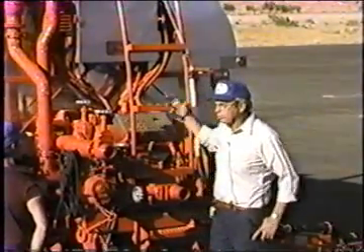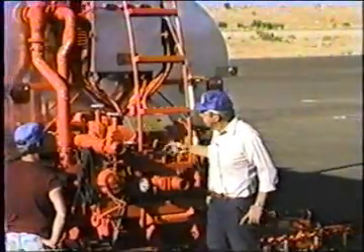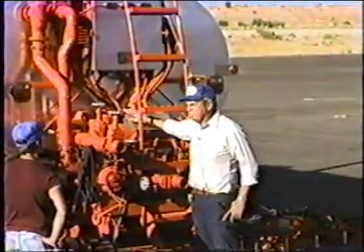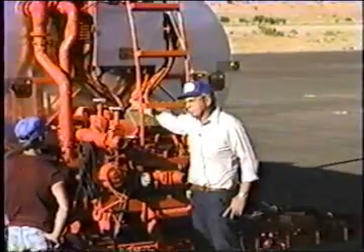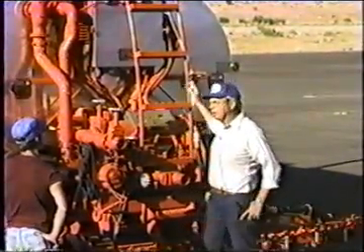If you don't have someone else around to point it out for you, you can find that one, clean it out. Then you have to go back to the cab, turn the front master switch off, come back here, turn this one back on, and now you're ready to go back to work again.